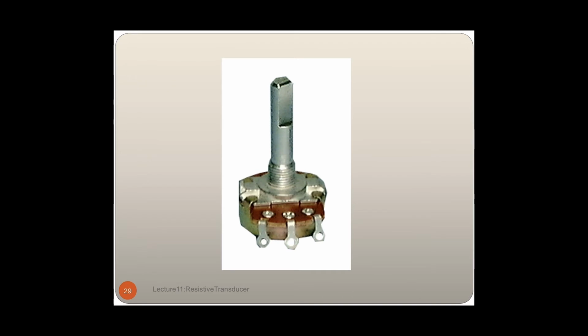And this is the simple potentiometer where we can rotate the knob. There are 3 pins on this potentiometer. Pin 1 is the voltage input. Pin 3 is for ground. And pin 2 is where we read the voltage output, depending on the position of the knob.